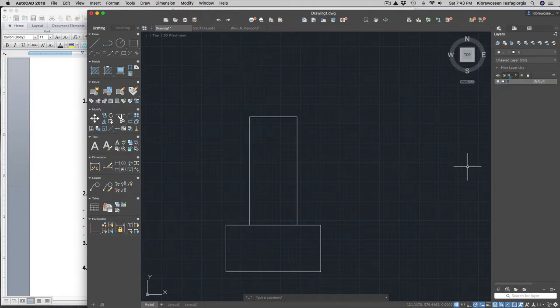Okay. But at the same time, do the following. Click on one and turn it on. Once you turn it on, you can press the space bar on your keyboard, right here. If I do that, then from stretch it changes to move. So by holding that grip, I can move this around. You see the way you see it.